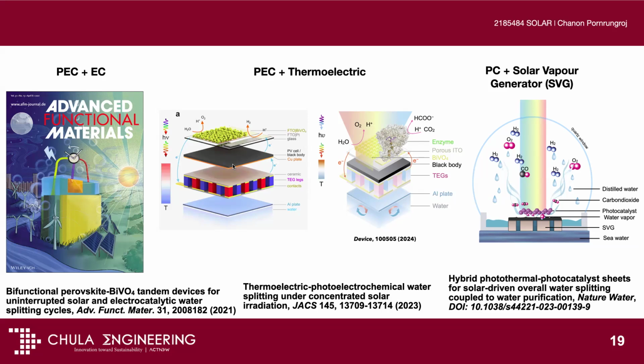But in reality, the problem is if you put thermoelectrics on the back like this, the thermoelectric heats up a lot, and then the panel also heats up a lot, and that heat reduces the efficiency of the solar conversion, and for many people, this idea became obsolete. I think people were doing this like 10-20 years ago, and then they found out that it doesn't work, because the panel, instead of, let's say, 20% conversion efficiency, reduced to 16%. It's not worth it, and you have to put thermoelectric material, which is also expensive, on the back. So people gave up on that idea.